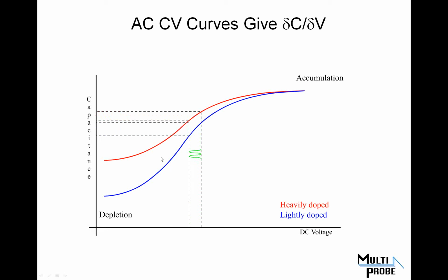And depending upon the CV curve of the structure that's being measured, you'll get, say, a larger signal or a smaller signal. What's not shown in this particular animation is, this is an N-type curve, there is a P-type curve, which would have opposite phase going away. So you would measure essentially a phase change. And so that's the difference between what we saw in the previous images of a green versus a blue. Those are simply different phases, because holes will respond in one direction to a signal, and electrons would respond with a different motion.